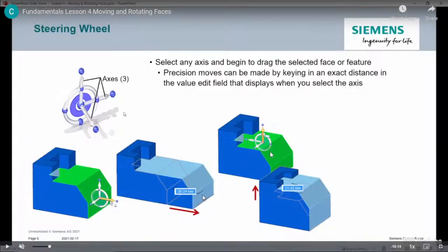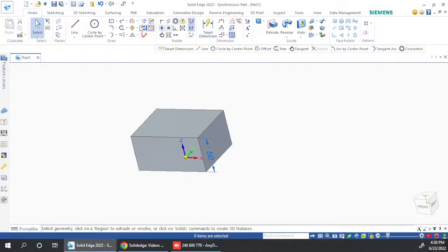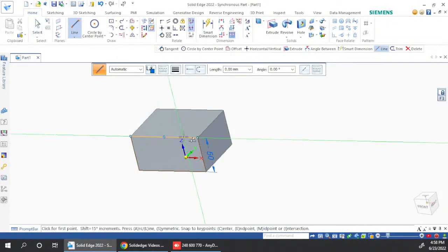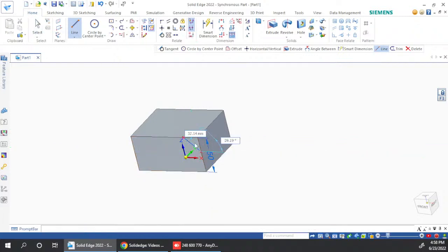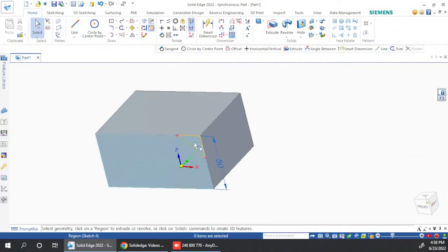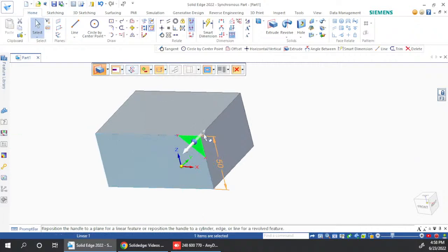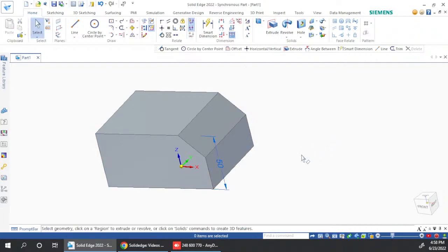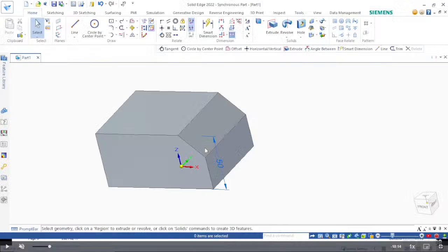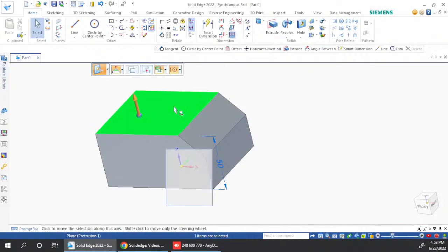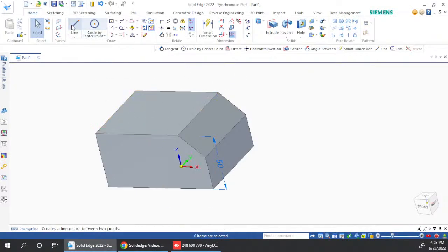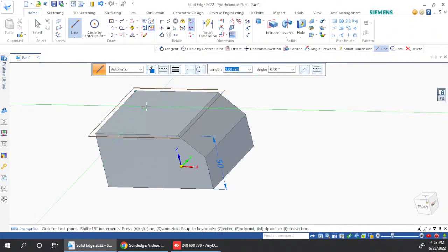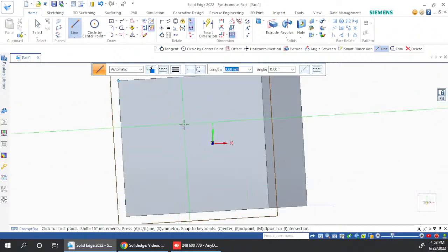Okay, so here there is a small chamfer. Either you can draw a line here on this face, lock this, draw a line from this point to this point, and as soon as you are done with the line, you can select this face separately, and if you select the negative zone, you can just go ahead and subtract this. Then we need to build this face over here. So select this face. We'll have to lock onto this face. So let me take line, hover over this, press F3 to lock it on. Go to top view. Okay.